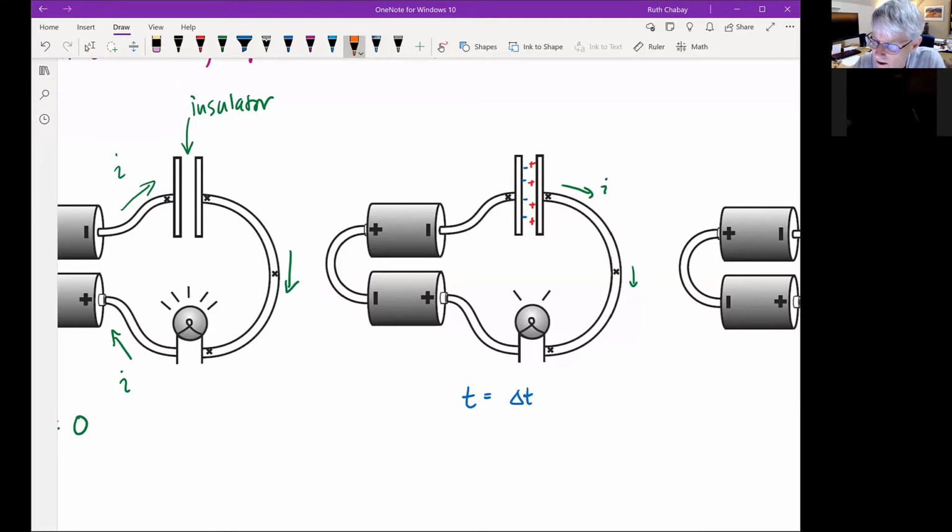And it's actually making a dipole field outside the dipole here. So we've got E capacitor here, and that means that it's actually going to repel the oncoming electrons in this electron current, which means that this current is going to decrease slightly. So I decreases, and the electric field of the capacitor increases.